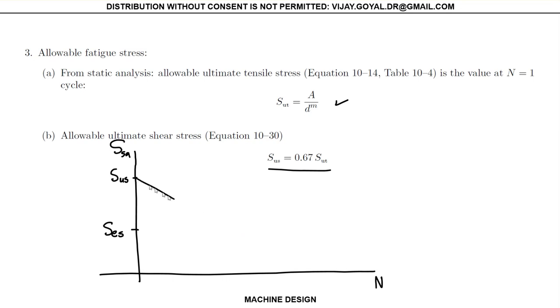So your fatigue diagram is going to look something like this probably, your life diagram. And we will talk about what this diagram actually is going to look like. It is going to be a little bit different for these materials because then we have to, actually it's going to be Fs, and this is defined at infinite life after 10 to the 7. But we will get to that in a sec.